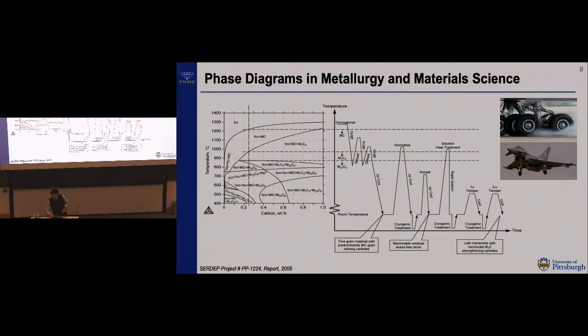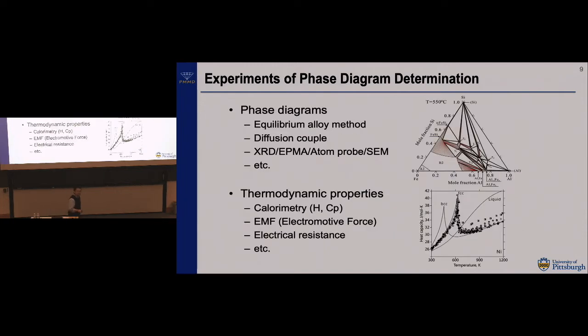All right. Since it's a very important thing, how can we measure it? So for the measurement method, you can think about this ternary phase diagram: alumina, iron, silica. You can think about vanilla, chocolate, and sugar. It's the same, right? So you just change the temperature, and you will have different phases appearing. So solid phases could be different with different crystal structures. If you have a different crystal structure, most likely you can identify it as another phase.